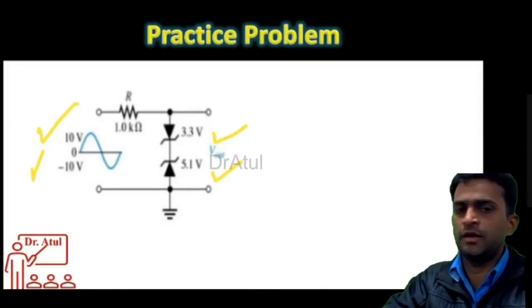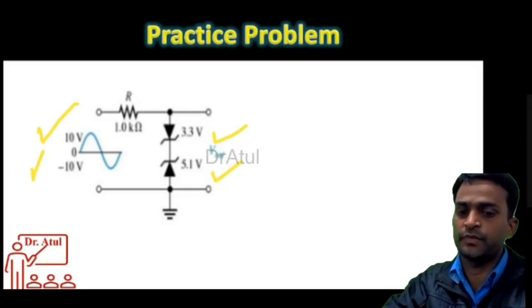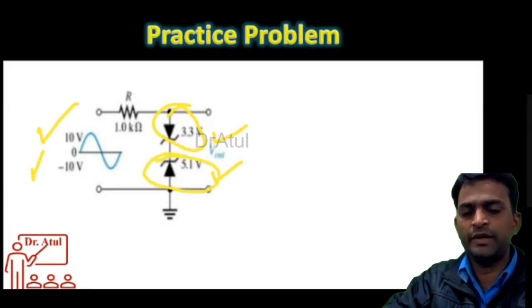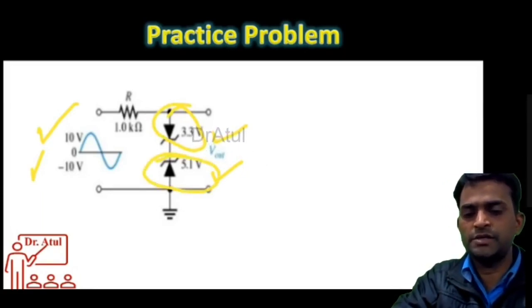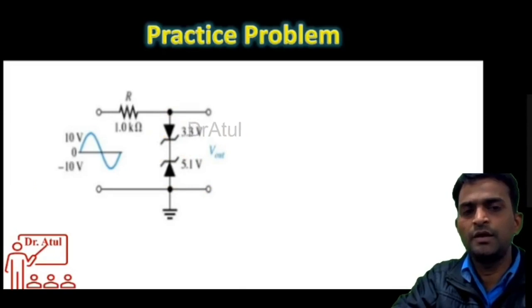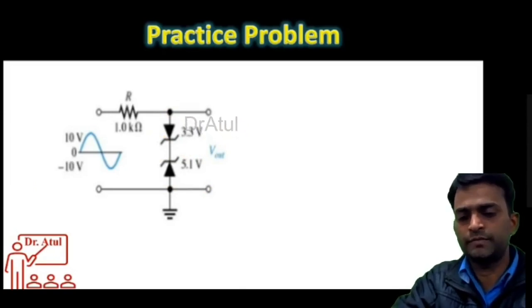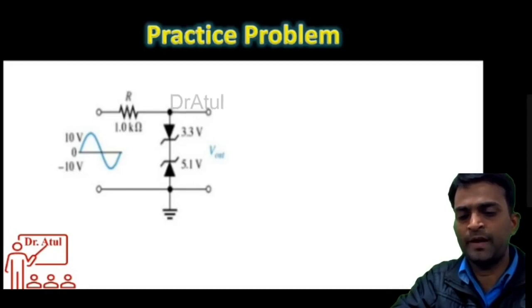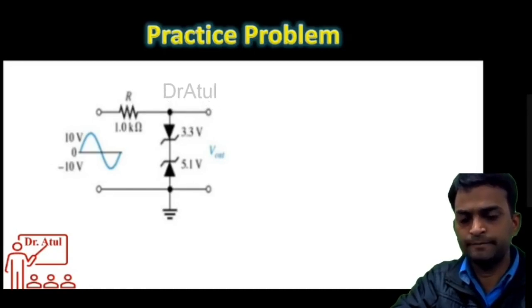This might be a forward cut-in voltage. This forward voltage cannot be more than 0.7 volt. Therefore, whenever any voltage greater than 0.7 volt is mentioned near a diode, then this voltage is the cut-in voltage. In the Zener diode, usually they mention the Zener voltage. So here you see that in the forward bias, there is no mention of cut-in voltages.